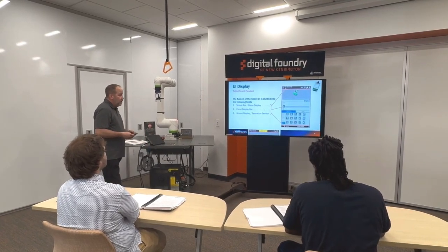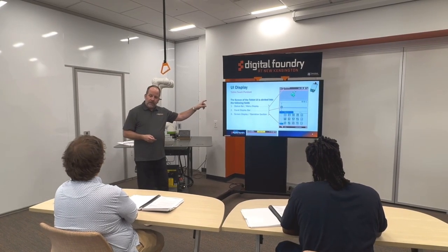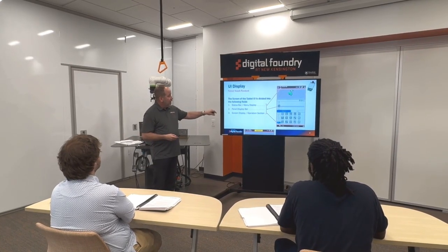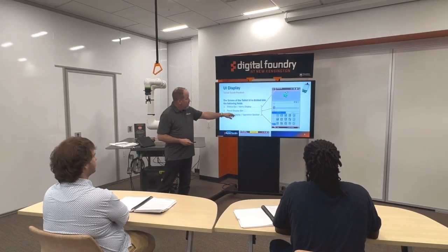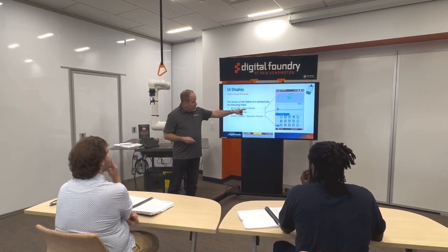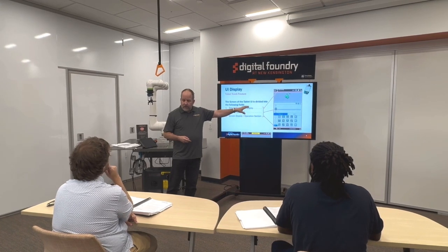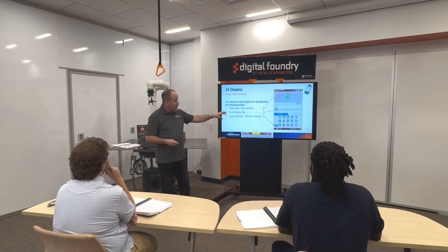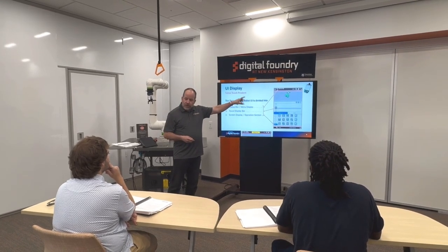So, the tablet Teach Pendant has a UI display, user interface display, as you can tell here, and it's broken up into a couple of sections. It has its status bar, menu display, and that's up here at the top. Then it has a panel display bar, and that's in the middle. And that usually is where you have the programming language, which is basically the icons that you drag up, and I'll show you that here in a little minute, as well as a graphic of the actual robot, which can show a number of things.